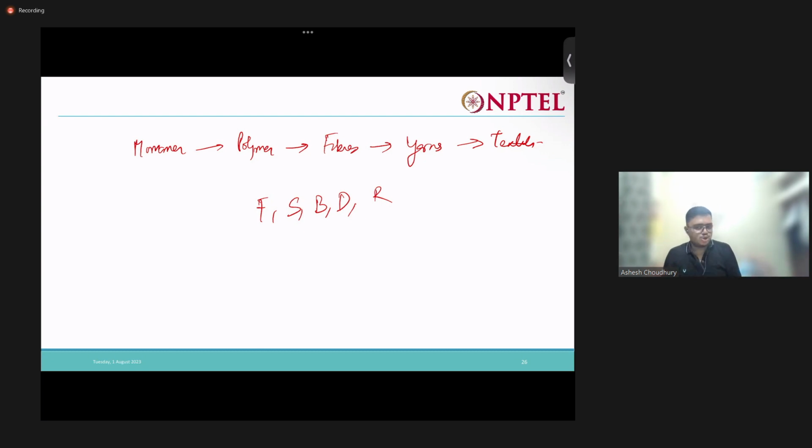No, right? Geomembranes cannot be used for drainage purposes or filtration purposes. For that, you have to use geonets or geotextile. What is the use of geomembrane? Geomembrane is only used as a barrier. Nothing else. It has just one purpose, that is barrier. So you always remember all these functions: B, D, E, F, P, R, S. Barrier, drainage, erosion control, filtration, protection, reinforcement, separation.